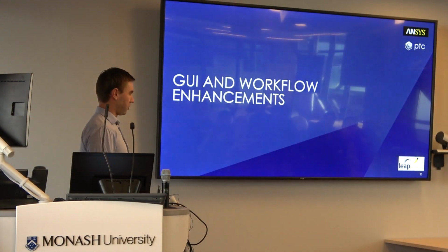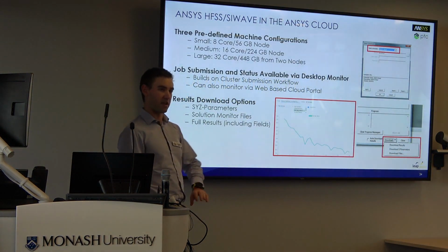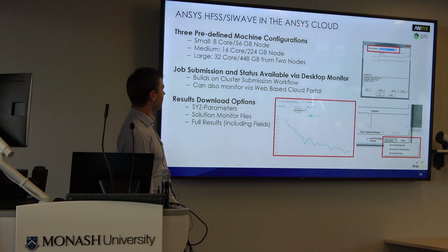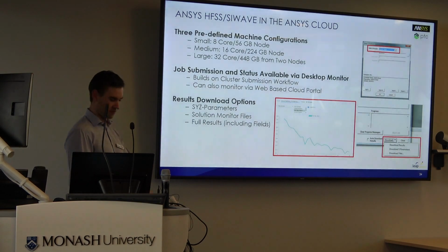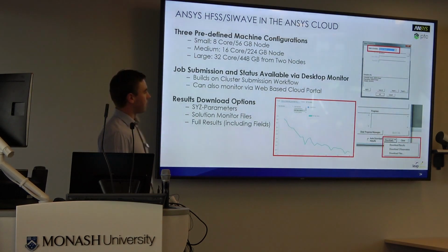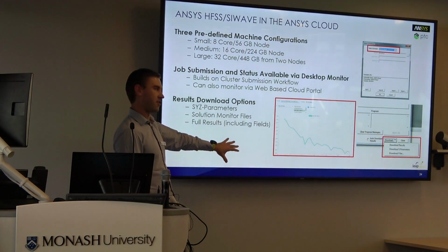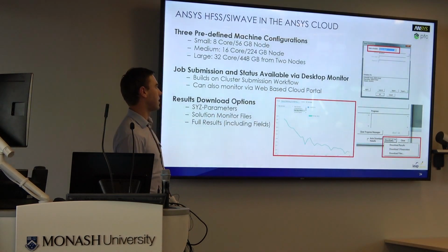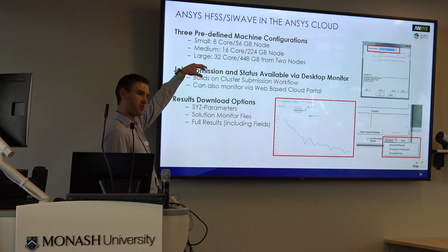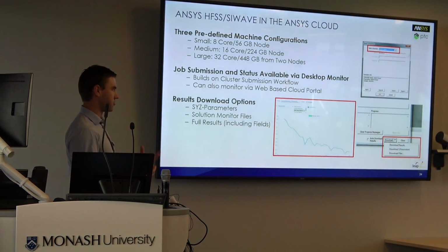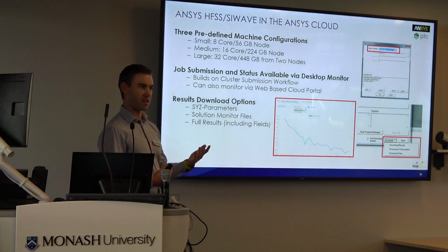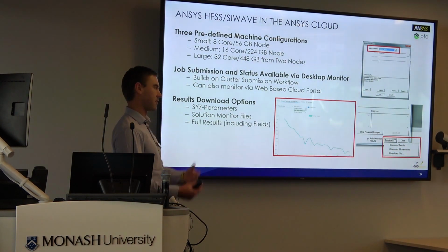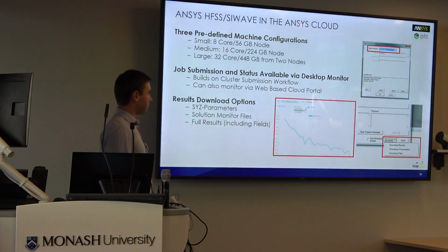So if we look at purely GUI workflow, this is usually where you save most of your time. The first thing people usually ask about is what can we do with the ANSYS Cloud? And so as of tomorrow, we can now use ANSYS HFSS and SIwave as part of a cloud solve. We have pre-configured node options, so this saves you all the time usually if you've ever used AWS or something where you've got to create an instance, set up storage, load the right image with ANSYS installed, set up licensing, and all that kind of stuff.